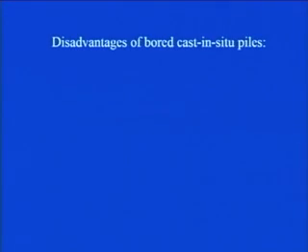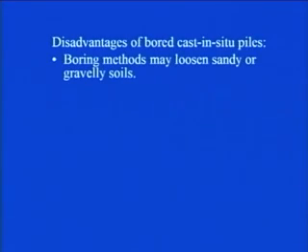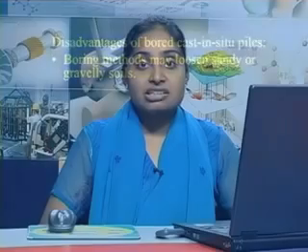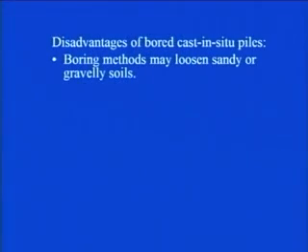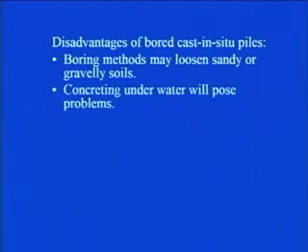Now, some of the disadvantages of bored cast in situ piles: boring methods may loosen sandy or gravelly soil. See, if the soil is clayey in nature, then these bored cast in situ piles are quite advantageous. But in case of sandy or gravelly soil, in the process of boring or excavation or creating the void, there can be loosening of the soil strata, which is not at all desirable as far as construction is concerned.